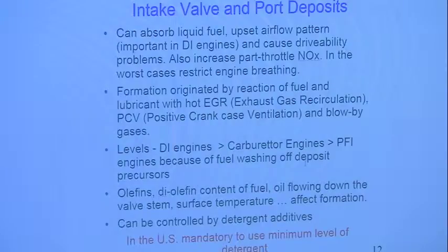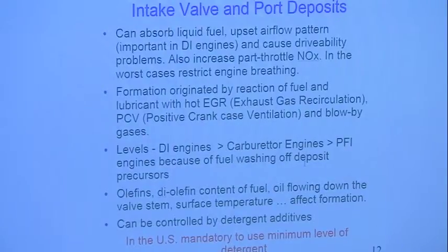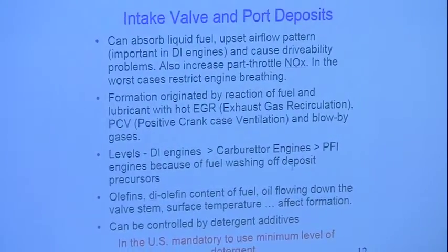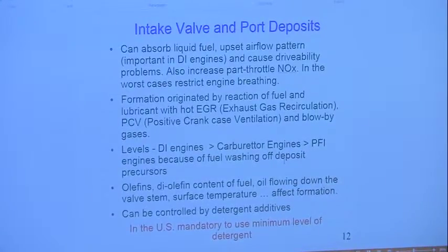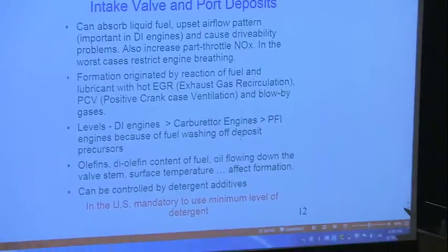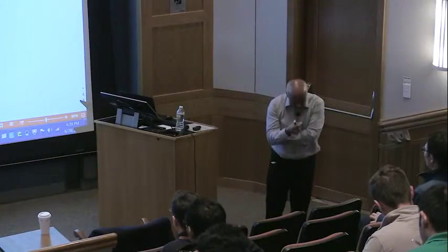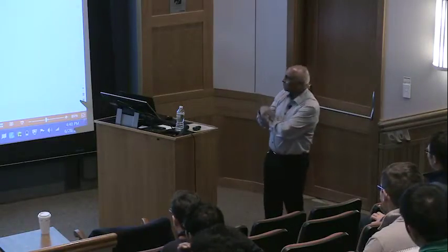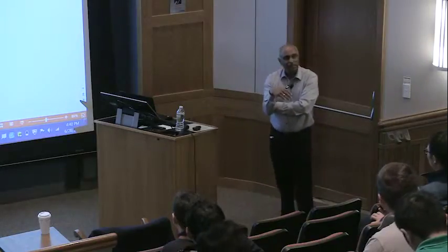In terms of intake valve and port deposits, as I said, if there is a port fuel injector, they can absorb liquid fuel, upset the airflow pattern, cause drivability problems, and also increase part throttle NOx. It's very interesting. In fact, this is one of the reasons why in the US, the US EPA has mandated the use of detergent additives in order to control port fuel valve deposits, because they said it increases NOx, and the mechanisms are not very well understood.